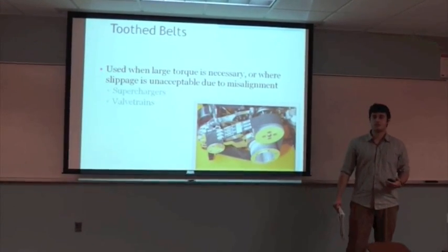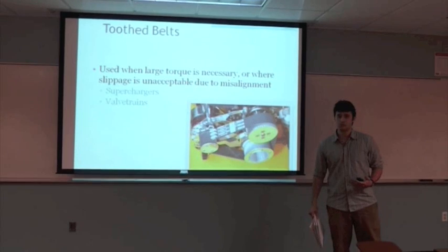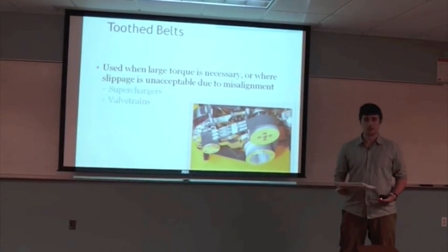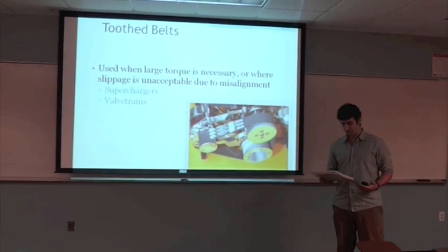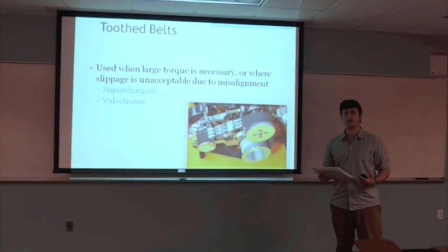Typical applications of a tooth belt would be to drive something like a supercharger, which requires a lot of power and would cause other types of belts to slip, or else to drive cams in a car's valve train, where you can't have any slippage in the system.